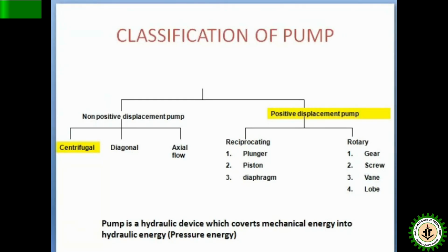When that fluid comes through the volute, because of the gradually increasing cross-section area, the kinetic head gets converted into pressure head. The rotary part of the pump imparts kinetic energy to the fluid, so the fluid has very high velocity. Once that high-velocity fluid moves through the volute, the casing of the pump, with its gradually increasing cross-section area, you know the continuity equation: increasing cross-section area means reducing velocity. And you know Bernoulli's principle: once the velocity is reduced, the energy has to convert to the other form, that is pressure energy. So that is the main role of a pump.